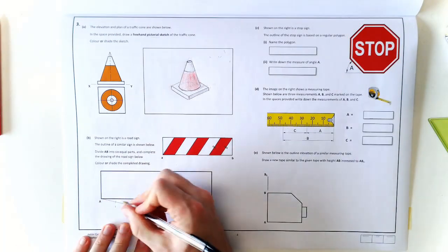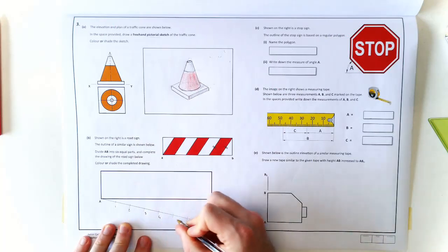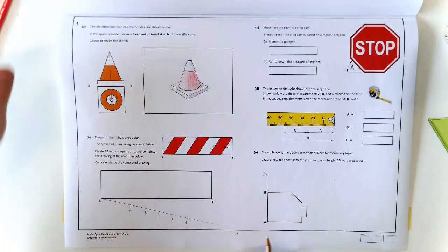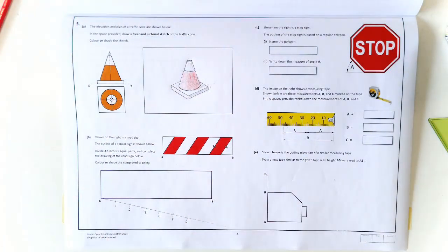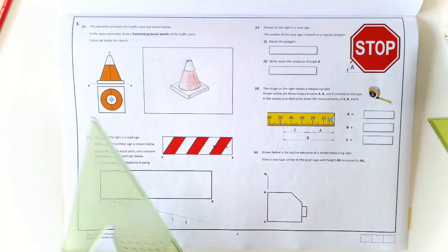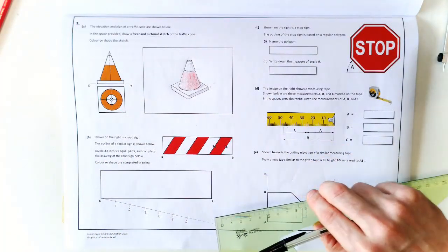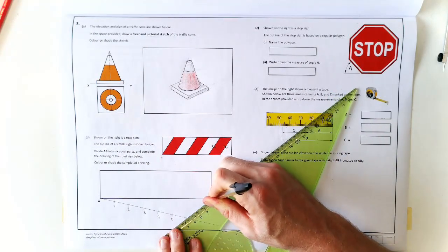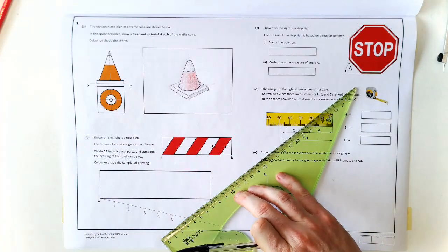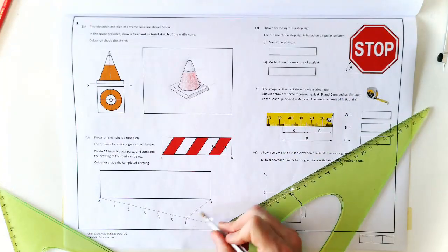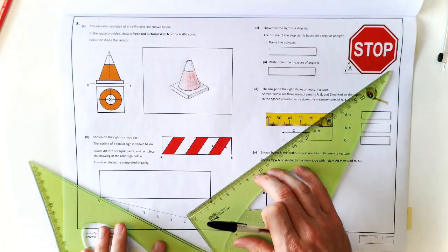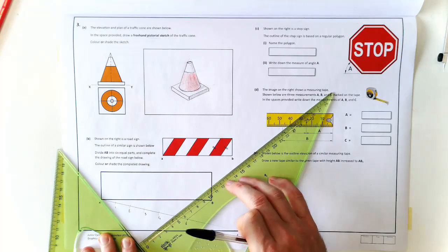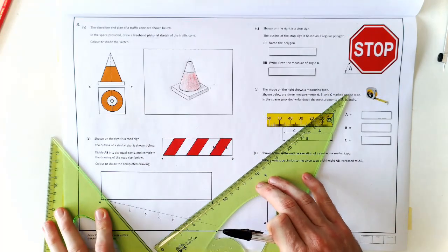And always, just for yourself, come along and label those just to make sure we've got our correct amount. Okay, common mistake there. People might know the construction, but just in the rush of the exam, get that wrong and maybe only do 5. So now I've got that done. My important line is going to be from that 6 point back to the end of the line I'm dividing. So there we have it. Okay, and what I want to do is that line I'm going to run parallel back from each of those marks. So here we have it. We're going to go parallel.